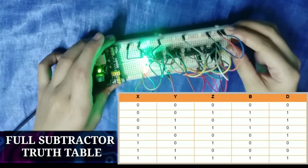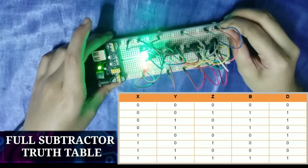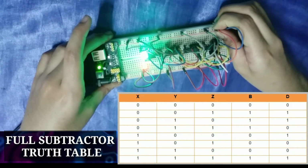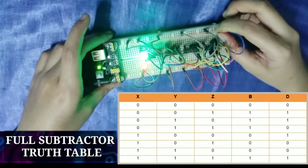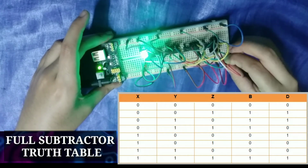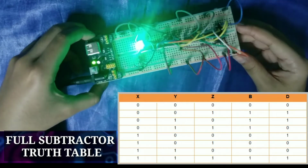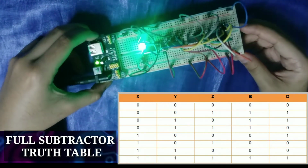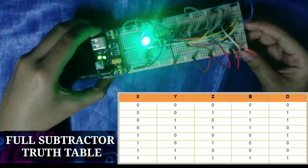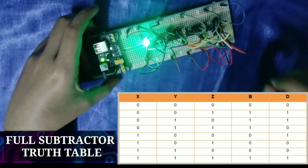Now, if only input X, or the blue wire, is a 0, and both of the inputs Y and Z are at 1, okay, let's put it here on the other end, as you can see, only the green LED turned on, or only the B output, the borrow output, turned on at logic 1.